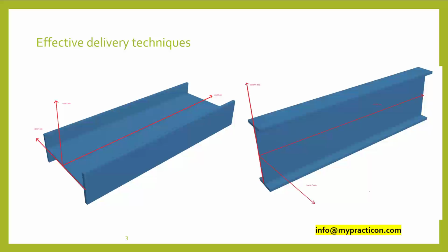It automatically does the force calculations, like wind load generation, and member design, everything. But as an engineer, what we have to do is align these members, oriented in the direction of the force or in the direction of the exposed areas, which is critical for steel design.